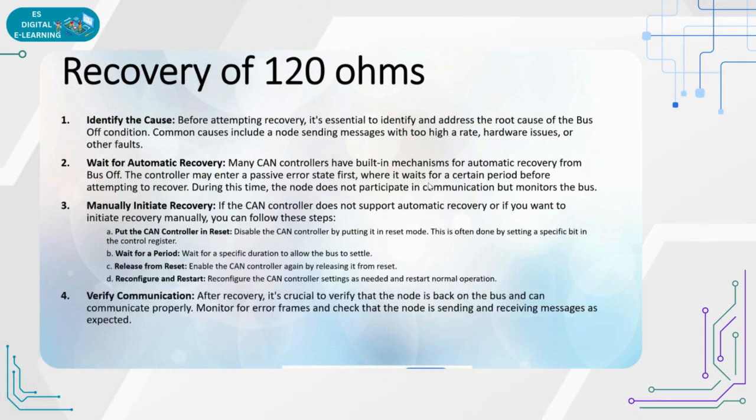So how will you do this automatic recovery of the bus-off error? Sometimes they will ask you these questions also. Physically you will verify the network. If no communication is happening, we'll see the physical level first. Coming to the wires, we'll check the 120 ohms, whether it is working or not. Once the hardware part is clear, then I will verify at the software level. From the software, I will just wait for some time to recover automatically. Like that, you need to give the answers.